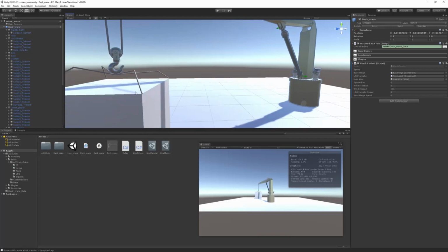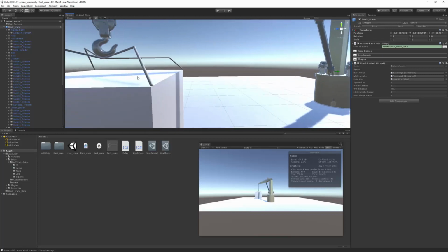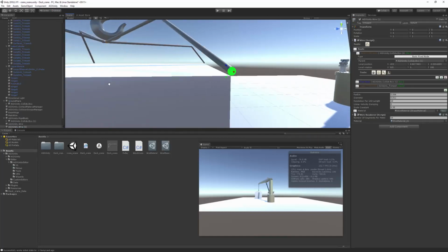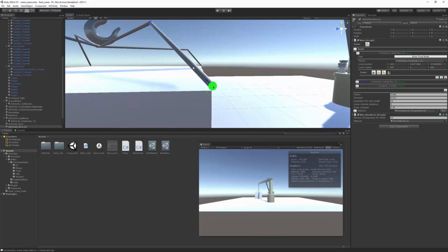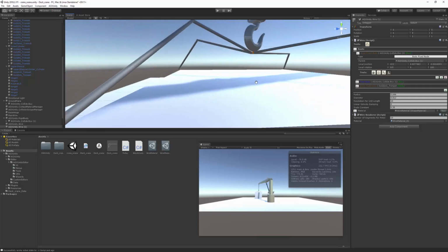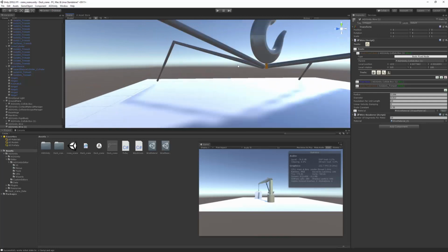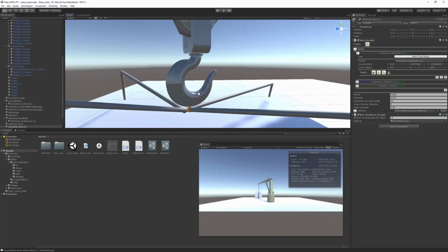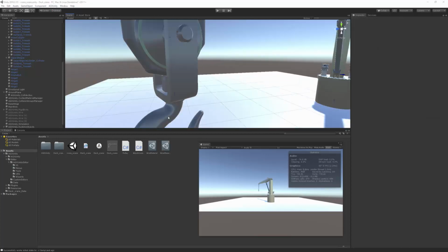It's important when you model a wire that you don't have the wire penetrate the attached rigid body. So here we have a body fix node, and we have to make sure that the wire is not inside of this geometry, because that will create contacts which will try to push out the wire at the same time as it is attached rigidly using a body fix node. So we have to make sure that this wire is slightly outside. Otherwise you have to disable collision between the wire shape and this geometry. We have done the same thing for the hook here. We have just moved the attachment points slightly outside of the hook.